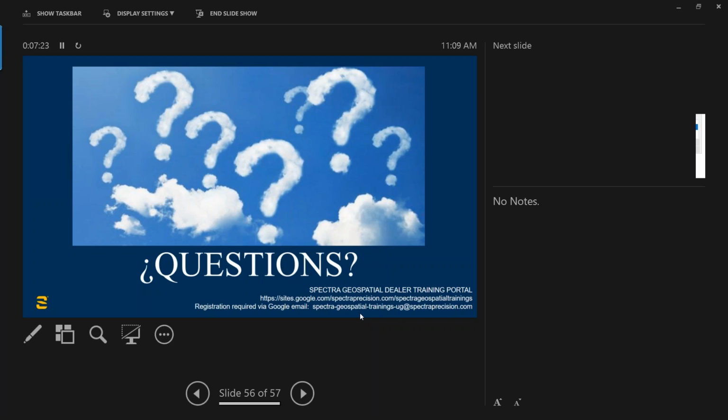You always want to do that shift to account for the bias in your local elevation to the geoid model mean sea level. There's always a bias there, but in my opinion, you're better off to use the tilts built into the geoid model than to try to do better with measurement on GPS control points. Again, especially, I mean, it's 2020 now, right? This would have been a different answer when I first started working for Trimble and surveying 20 years ago when we had Geoid 96, but with Geoid 18, it's in good shape. Right.